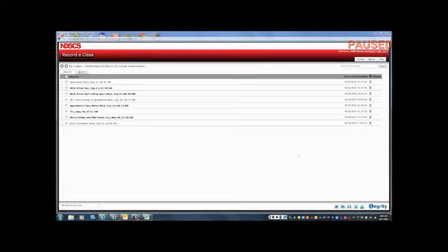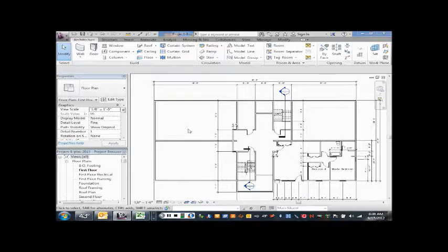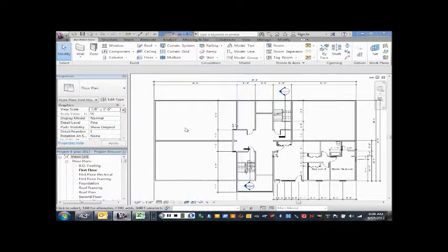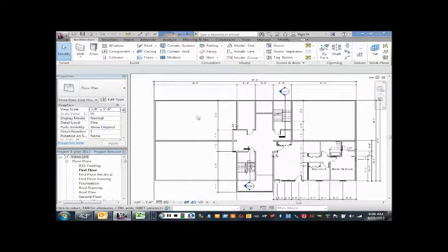Okay, so let's talk about putting a floor system in. In this case, we talked last week about what the floor system is made out of: it's 18-inch deep floor trusses with 3/4 inch tongue and grooved subfloor on top of that. And then on top of that, there's going to be 1 inch of gypcrete, which is a fireproofing, sound deadening layer.